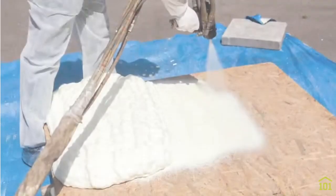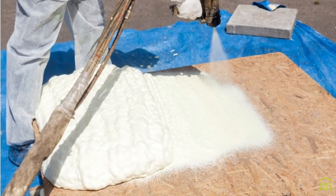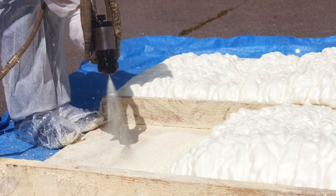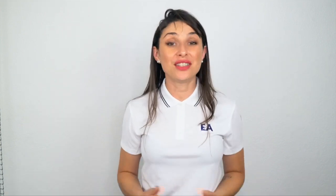This is a popular roofing option for flat roofs because it simply adds extra protection. SPF is a spray applied material that is made by mixing chemicals to create foam. This is applied with spray equipment, providing a roof covering that can go over an existing roof and over new construction. SPF is widely used because it insulates the building, seals cracks and gaps, making the building more energy efficient, and of course, providing a moisture barrier.